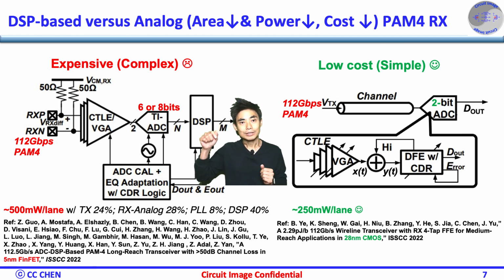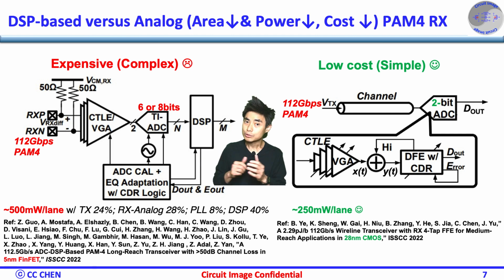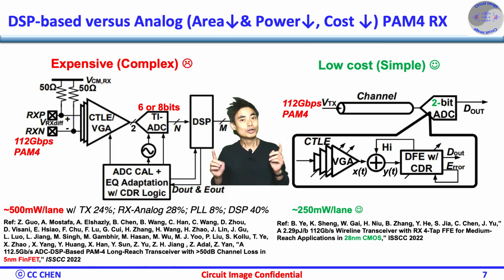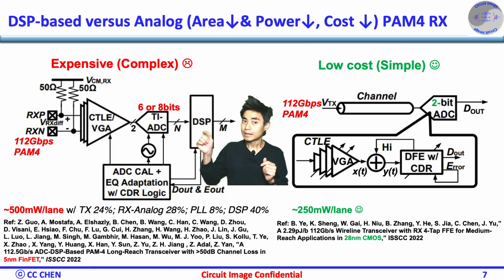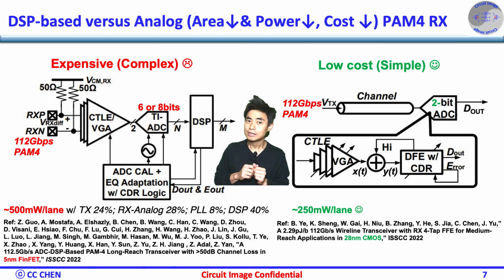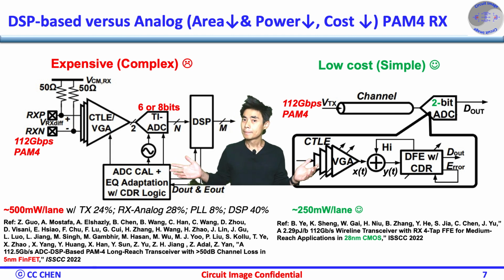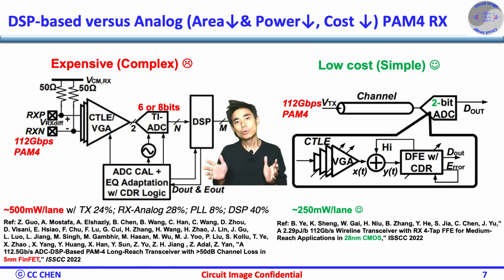Furthermore, the low power advantage would also help the PAM4 RX be suitable for power-constrained applications and have long-term reliability with less aging stress than the higher self-heating of a high-power DSP RX, which may degrade the performance over time. Therefore, it's not practical to see much DSP RX used in an old technology node, since the power was too much.